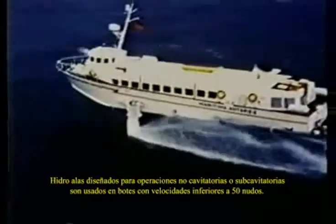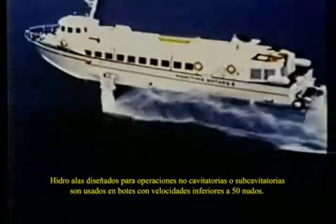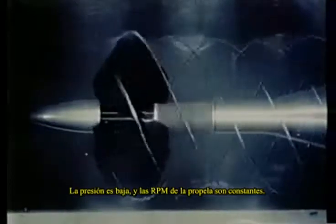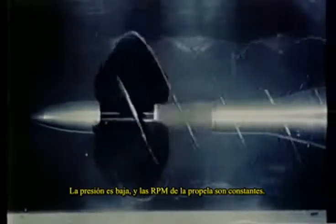Hydrofoils designed for non-cavitating or subcavitating operation are used on hydrofoil boats at speeds below about 50 knots. Let's look at the propeller model again. At this point, we want to emphasize the role of the ambient pressure. The pressure is low and the propeller RPM is constant. Notice the cavitation on the blade faces as well as in the tip vortices.